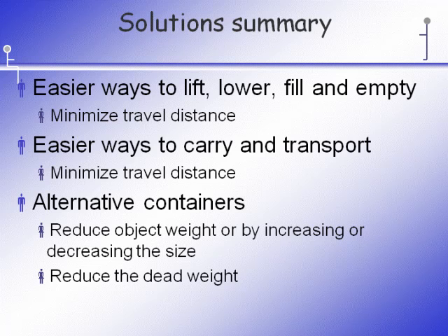Can you change your container? Can you decrease the dead weight, put whatever it is that you're carrying in a lighter container, and change the characteristics by which the hand comes in contact with the container? Are there cutouts? Can we get the load close to the body? Or can we maybe increase the dead weight? That's instead of getting bags of flour in 50-pound bags, let's get them in 500-pound boxes, and therefore there's no way for the person to pick it up without the use of a manual materials handling aid.